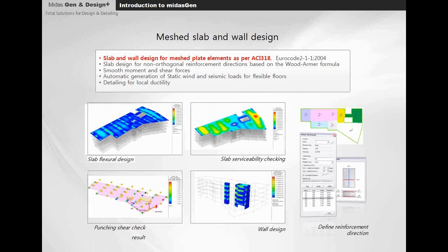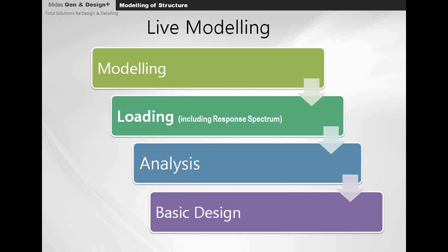As I mentioned before, MIDAS Gen also supports mesh, slab, and wall design apart from its analysis features. Shortly on your screen you will see the slide. We have mesh slab designs as per plate elements for the American and the Euro codes, and you can design for non-orthogonal reinforcement directions based on the Wood-Armer formula.